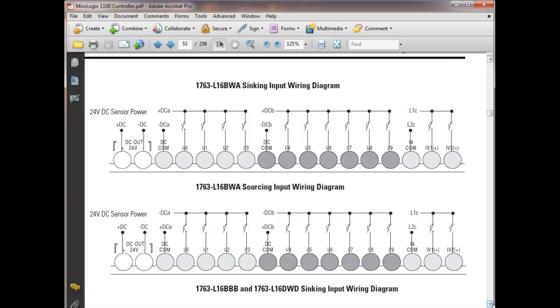Of course, here we talk about limit switches and all this kind of stuff, but when you get out there, we might have limit switches, but now the predominant sensors are electronic sensors. And they're going to give you a DC. Most of your sensors are DC. We got some sensors back here that are DC, and since our motor controls is 120 volts AC, what they did is they put little relays on the modules themselves. So we can plug them into 24 volts DC, and then the output of the sensor turns on a relay.